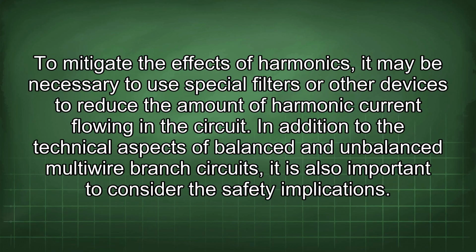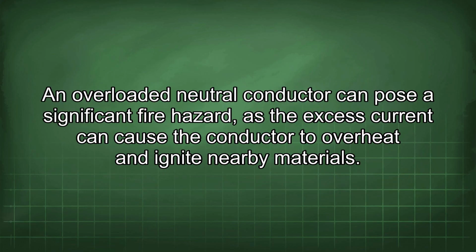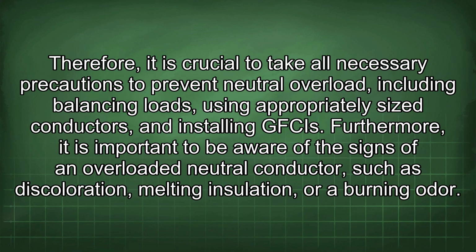In addition to the technical aspects of balanced and unbalanced multi-wire branch circuits, it is also important to consider the safety implications. An overloaded neutral conductor can pose a significant fire hazard, as the excess current can cause the conductor to overheat and ignite nearby materials. Therefore, it is crucial to take all necessary precautions to prevent neutral overload, including balancing loads, using appropriately sized conductors,